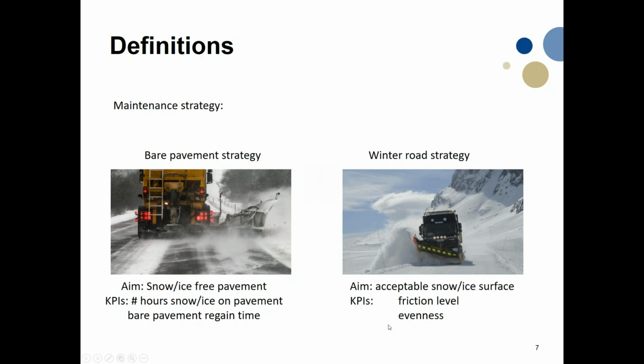Now, the reason why I don't like anti-icing as the word for the strategy is that it is also used for an operation. And if you talk about anti-icing, you always talk about de-icing. And to call this de-icing is not really true, because actually we don't necessarily want to de-ice. We just want to allow the traffic to drive on a snow and ice surface. So that's why we, at least in Norway, prefer to use the terms bare pavement strategy, as opposed to winter road strategy.